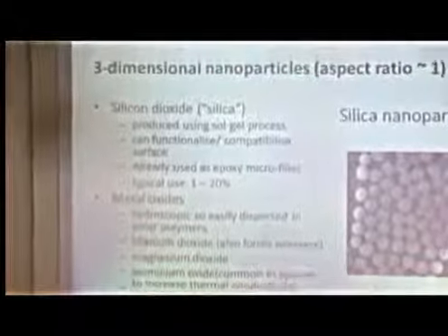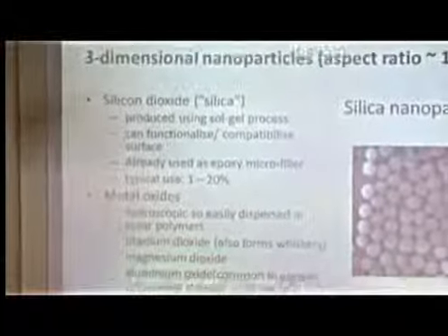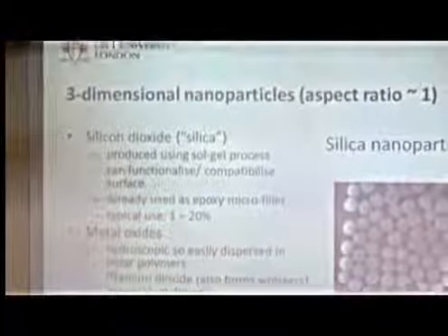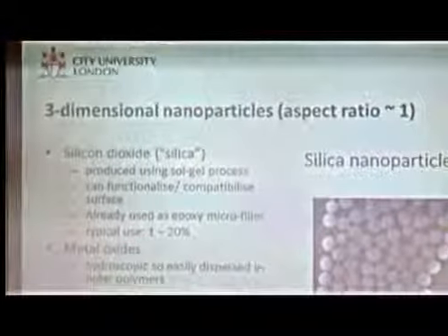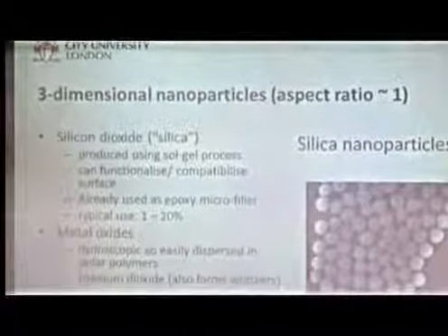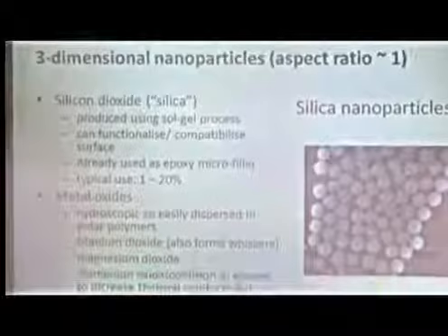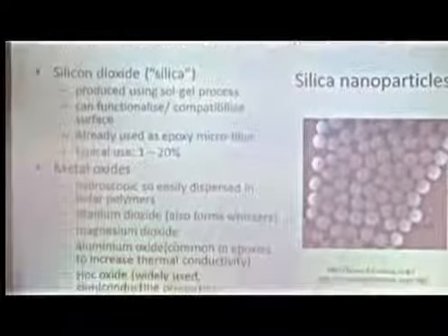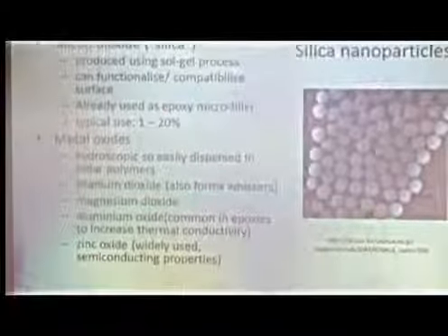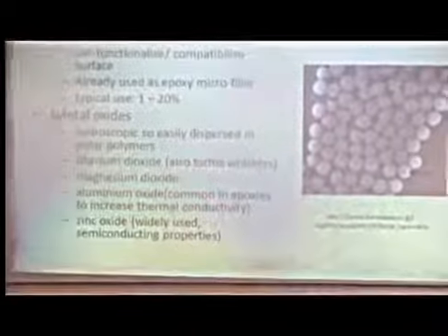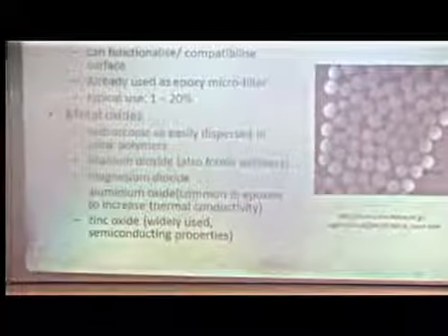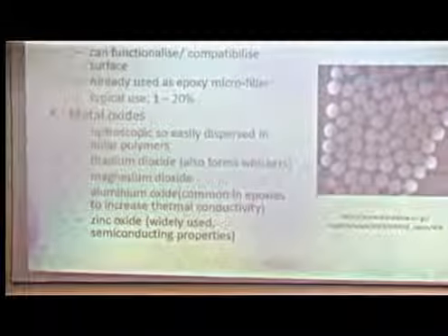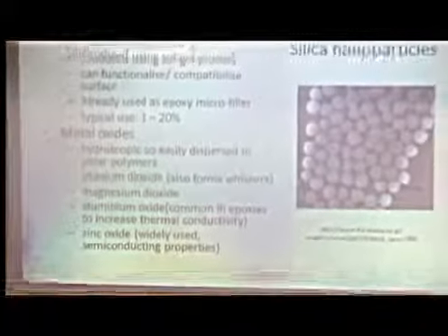So if you look at a typical epoxy that's used for, I don't know, bread and butter, low voltage insulation systems, often in low voltage distribution systems, then it's often coloured red or something like that. Then it's often full of sand, basically, and indeed it's almost sand stuck together by epoxy, and so there'll be a lot of silica in that.